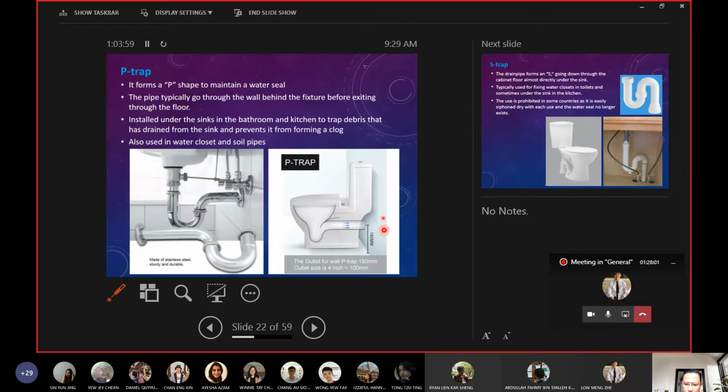You need to have the discharge pipe behind here, behind the wall. It cannot go inside the wall, because usually the soil pipe is bigger than the waste pipe. From here you can see that the waste pipe is quite small, so you can hide it inside the wall. You can knock the brick a bit, put the pipe inside the wall, and then close it with tiles. You cannot see the pipes. But the soil pipe is quite big.